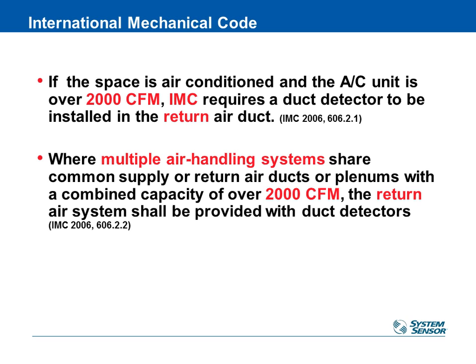majority of buildings. If the building is following the International Mechanical Code, now remember, it could be following the IMC by itself or at the same time as NFPA. That code also looks at 2,000 CFM, and that is the requirement for a duct smoke detector to be installed. However, the IMC requires it to be installed in the return air duct. So NFPA requires it in the supply, IMC requires it in the return. Both of them look for pieces of equipment that are 2,000 CFM.